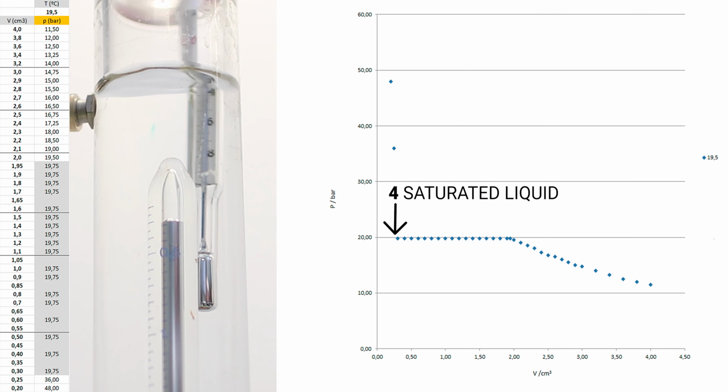The disappearance of the last gas bubble, resulting in a unique liquid phase. In this border state, we can say that the liquid, at this pressure and temperature, has saturated its capacity of maintaining all its molecules in liquid state, grouping some of them in the first gas bubble. We call this state saturated liquid. The liquid region, in which the fluid experiences an abrupt increase in pressure as volume is reduced at constant temperature. We denote this region as the compressed liquid or subcooled liquid region.